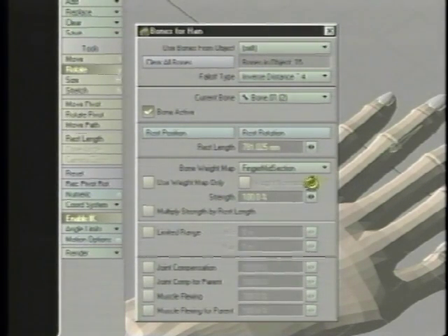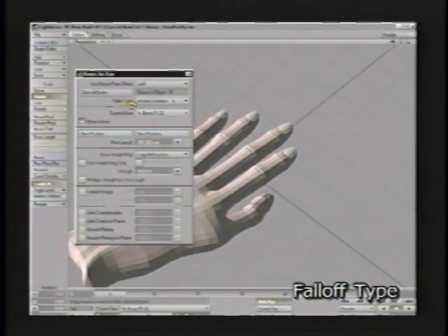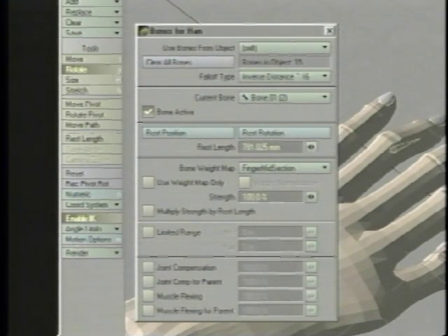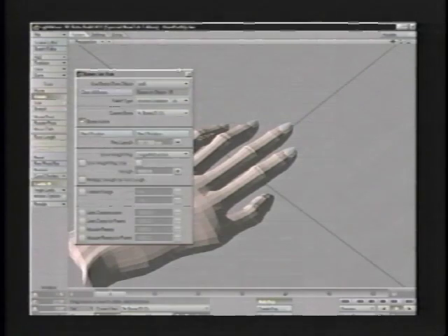All right, that's it. So one other thing I want to do, generally with fingers, because fingers are so close to each other, and we're sharing weight maps between the different knuckles, we'll set a falloff range a little higher so that the effect of the bones doesn't spill out across the knuckle joints. So to do that, we go to our falloff type and we'll just set it up to 16 and see how that works. And we go ahead and rotate that, and you'll see it's just affecting the appropriate section. It's not affecting the bones around it. Again, we can rotate that down.